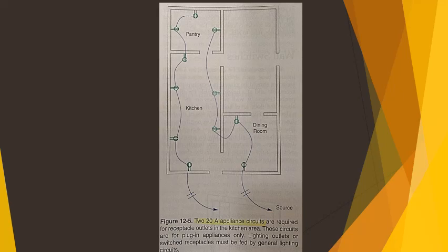Wire capacity. Although the NEC specifies 14 AWG as a minimum wire size, it would indeed be unwise to use anything smaller than 12 AWG in homes built today. Lighting and receptacle outlets wired with 14 AWG will almost certainly be inadequate in 10 to 20 years.